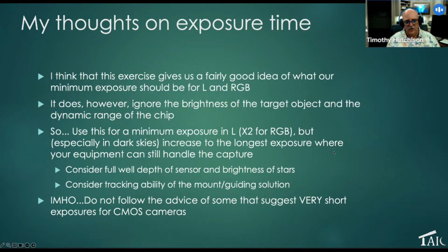But what doesn't it do? Well, it ignores the brightness of the target object, right? It doesn't even think about that. It doesn't even consider the brightness of the object that we're taking. And it doesn't even consider the dynamic range of the chip, which is finite, right? These sensors, remember, these are digital devices. They are not analog devices. They don't have an infinite dynamic range. They have a very, very finite dynamic range.